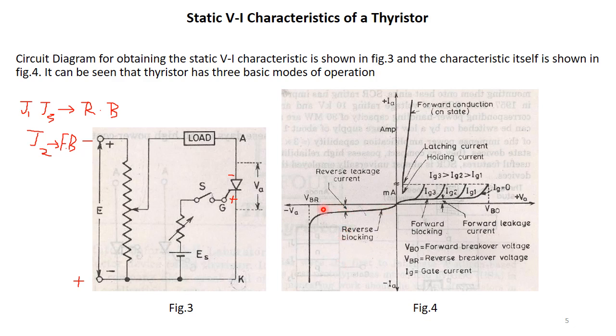The curve which has been shown in the figure is actually obtained when the load resistance is 0. Now, in case if there is some load resistance present, a large anode current associated with this breakdown value would cause a substantial voltage drop across the load, and as a result, in the third quadrant, the curve would bend to the right of the vertical line like this. The curve would be slightly like this. I hope it is clear to you people.